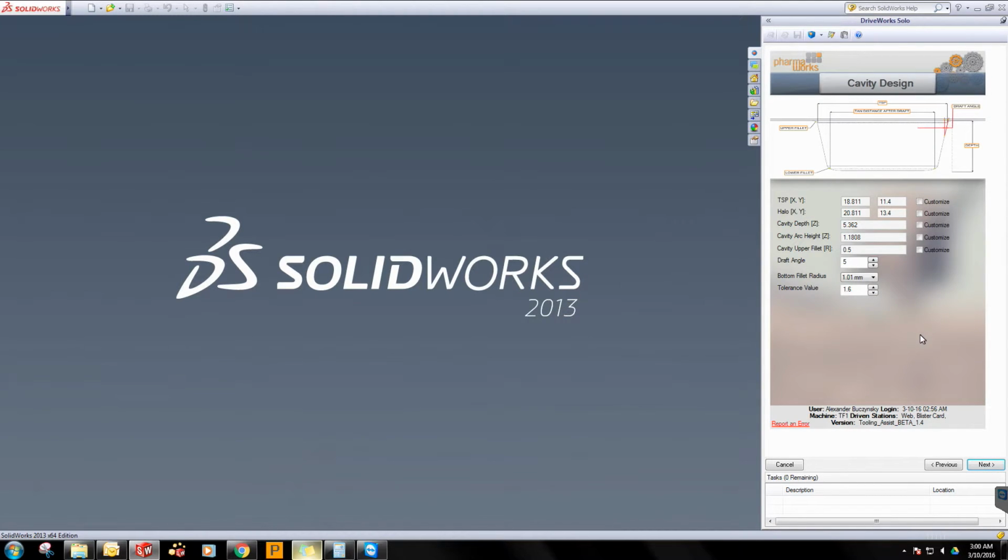So now we come to the manual entering part. So here the user sees all the values that DriveWorks automatically calculated. If for some reason any of these values need to change, they can be changed by going here and selecting the customize option, and then the user can go and select a different value that hasn't been calculated. So let's say instead of 18.8, we're going to round up to 18.9. Whatever those values are, the user can then choose that. So those customize buttons are there in case the program comes up with something that the user doesn't agree with.